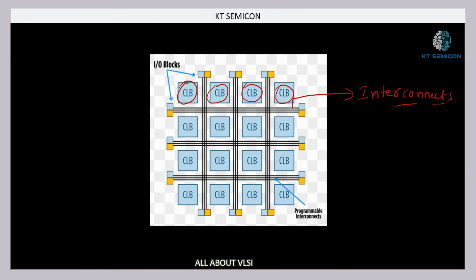Now, for example, if our FPGA wants to act as a UART controller, which is going to control a UART frame for filtering or removing any packets, that particular logic it can implement. Suppose it needs to act as a counter for counting the number of clock pulses, it can act. If it needs to act as a finite state machine, like a simple traffic light controller, or a vending machine, it can act. How that configurability is achieved by the FPGA is nothing but using these configuration logic blocks, connected using these interconnects.